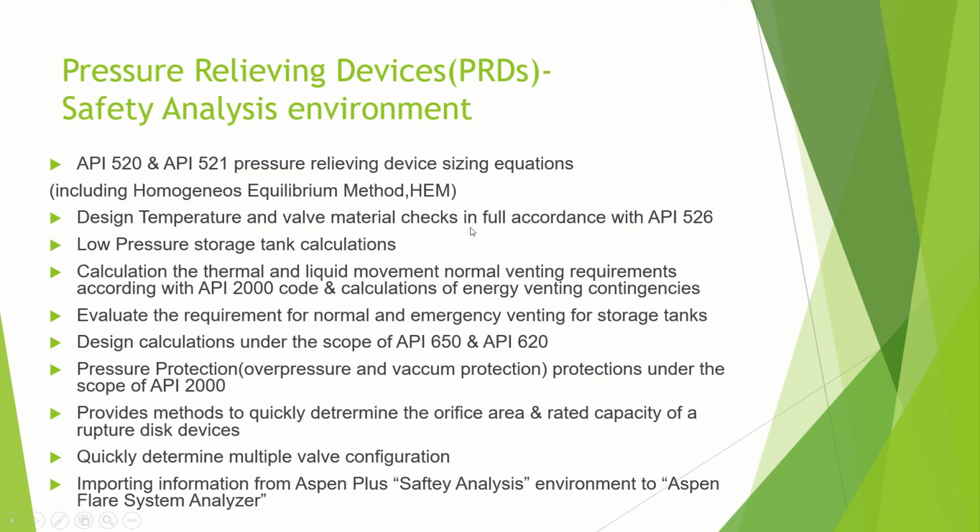First of all, I can explain the assumptions that are used in the safety analysis environment. API 520 and API 521 standards are used to calculate the pressure relief device sizing equations. Also, the homogeneous equilibrium method is used in this module. The other assumption is that the design temperature and valve material checks are in full accordance with API 526.